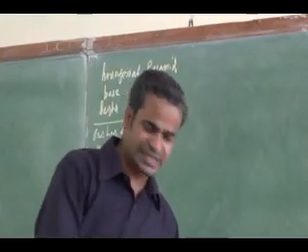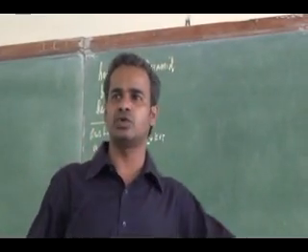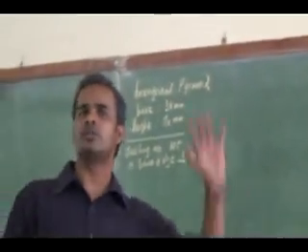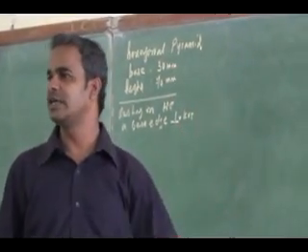That you know. So the true shape of the base should be such that one of the edges is perpendicular to VP. You have to draw the base of the hexagon. Then you proceed. You draw the top view. Then you proceed for the front view of the pyramid.